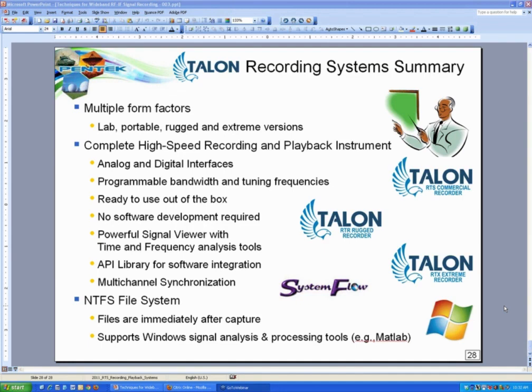We're currently limited by that primarily due to the PCI Express interface, Gen 2, which is the current interface that we're using. When we go to Gen 3 on that particular module, we will be able to get up to the higher rate of 3.6 and at 12 bits. So if you keep 2 bytes per sample, that's a 7.2 gigabyte per second stream, which is quite challenging. But with PCI Express Gen 3, you can achieve that. So I guess the short answer is not today, but it's coming soon.